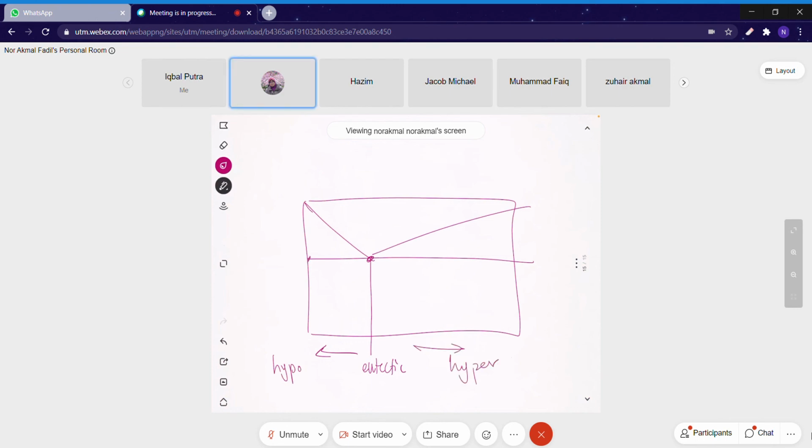As long as your alloy passes through this isothermal temperature, this horizontal line, the eutectic temperature, and the composition is within these limits, in this case 100%, from 0 to 100% bismuth if you add bismuth into cadmium, the mixture in this region is of course cadmium plus bismuth. But if you focus only on hyper, it is a mixture between this vertical line and this vertical line.